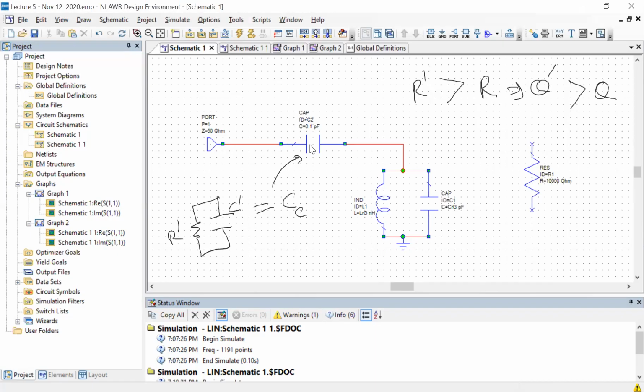So these are, once you work this out, good numbers to keep in mind. This is a good formula, so that you can very quickly know that, okay, if this is a 10 picofarad capacitor, if I put 0.1, I don't have to worry too much about the frequency shift, but you have to keep it in mind that this is going to happen.